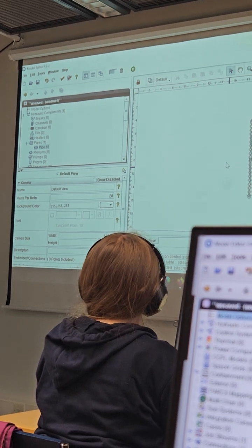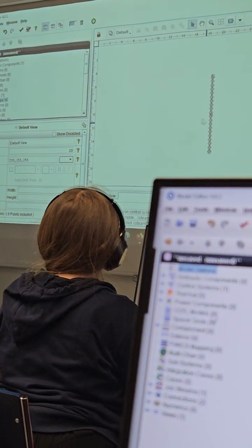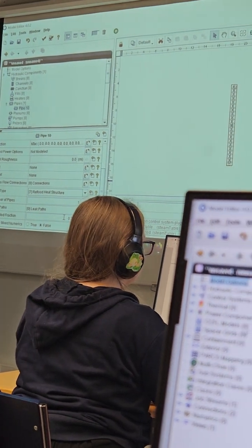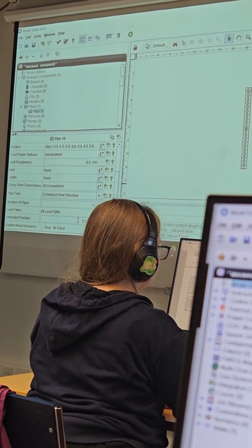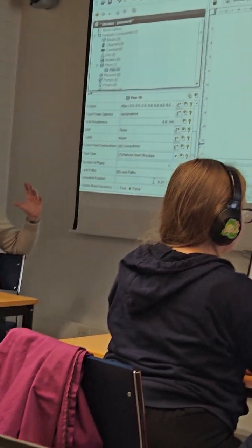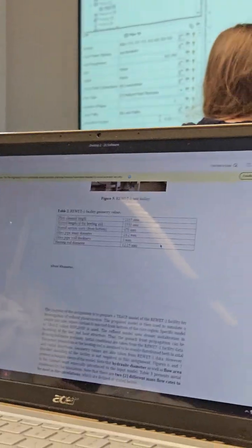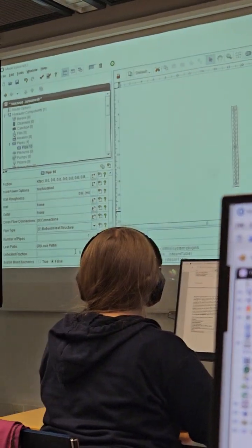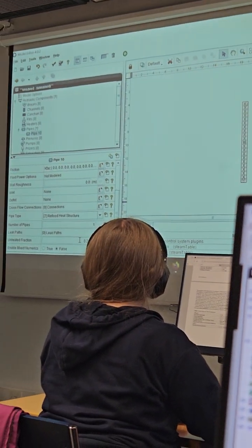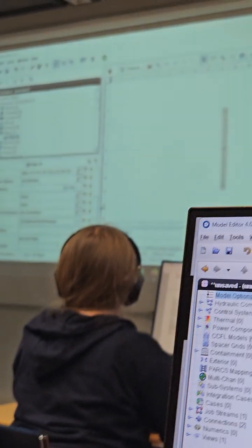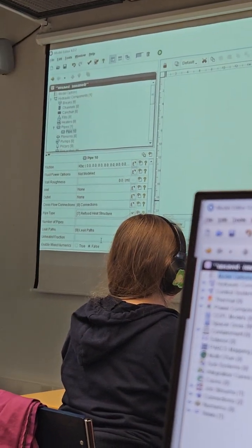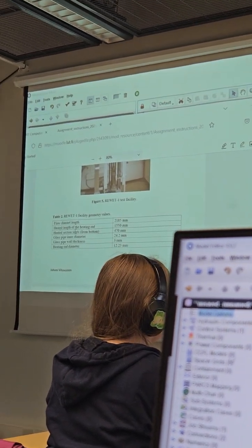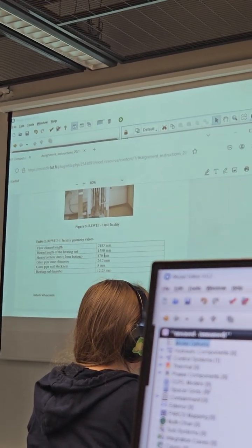Also, since we have to connect the heat structure, here, 0.20, heat structures to the pipe, we need to have a kind of well modelization, since it connects not like object to object, it connects node by node between the objects. The length of the nodes of the cells should be exactly the same for the heat structure and for the pipe. And also, we have one initial condition: the heated section starts from the bottom at 470